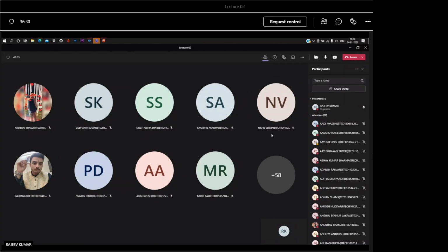Okay. T minimum equation, you tell me how much you have got? Sir, T was equal to WR upon 2L cos 2 theta sine square theta. So I put theta in that equation. And W, how much you have put? 1200. No. That will be shared by the 2, na? Yes. So it will become 600. Oh, okay, sir. Yeah, understood. Okay.